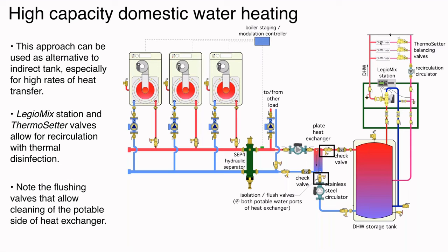I've had people tell me, these heat exchangers will foul out if you have hard water. Well, so will any water heater. If you have hard water, you simply can't complain that you're losing heat exchangers, whether they're internal heat exchangers, direct fire water heaters, or flat plate heat exchangers. You've got to treat the problem. Fundamentally, you've got to clean the water up or soften the water so that you're minimizing any accumulation on these.